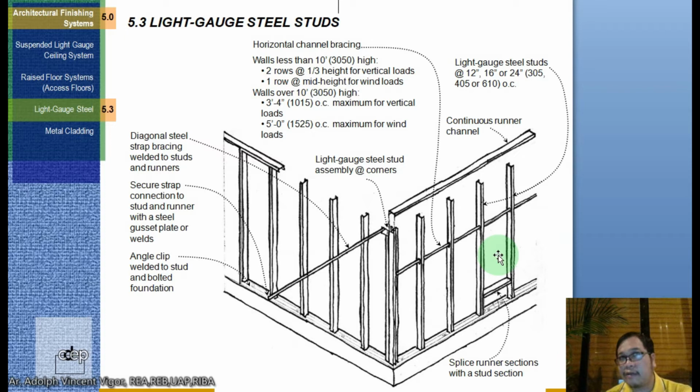In residential areas, a lot of contractors and even building owners find it more convenient to use hollow blocks, because hollow blocks already have good thermal and acoustic properties. Okay. But the advantage of this one is that it is cheaper if you exclude the filling in between. Okay. That's why this is ideal for office spaces and for areas wherein you don't need much acoustic consideration.